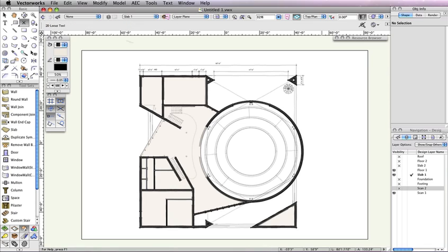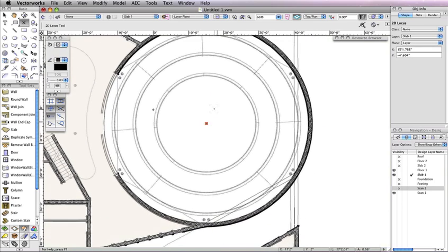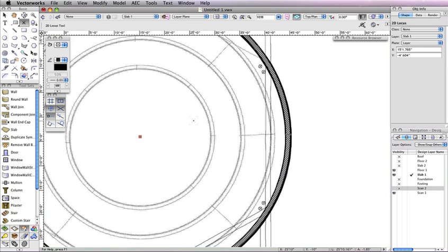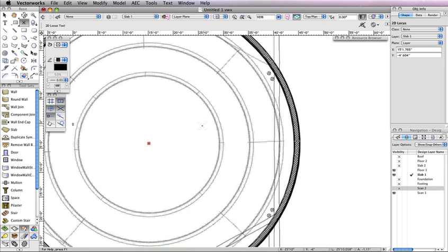Now, click at the center of the existing round wall, then the cursor cue Arc Center appears. After setting the locus point, zoom into view so that you can see the detail in the Floor 1 Scan in the auditorium. Pan if necessary so that the locus point is on the left side of your drawing area. Next, go back to the Basic Tool palette and select the Line tool. Then click to set the first point of the line when the cursor cue Arc Center appears.